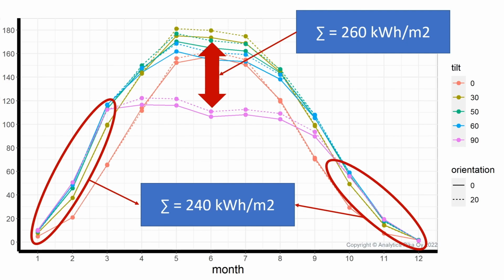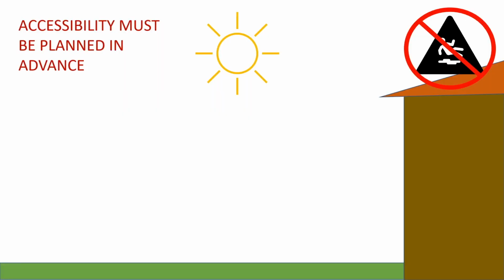To mitigate the losses of vertical mounting, simple engineering solutions exist, for example, lifting the panels 30 to 40 degrees away from the wall in the spring to achieve the optimum 50 to 60 degrees tilt angle for the summer season. It would mean repositioning the panels twice a year, probably a couple of minutes effort per module assuming cheap engineering. 20 modules would translate to about 2 hours labor per year.